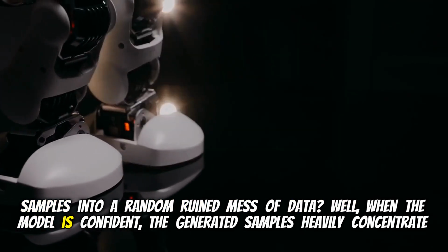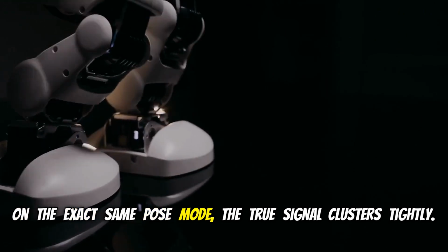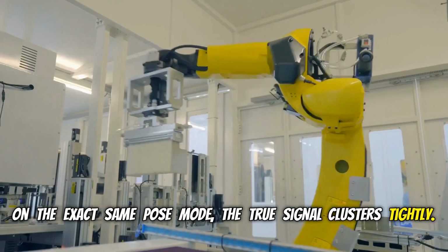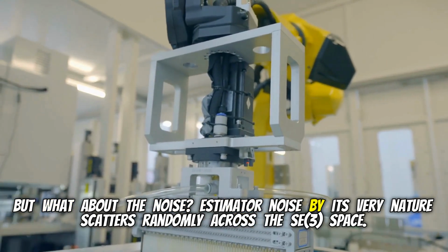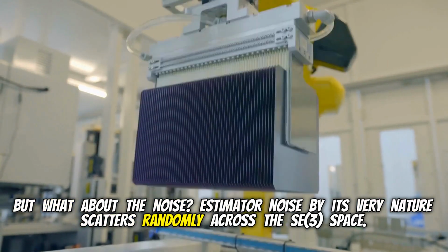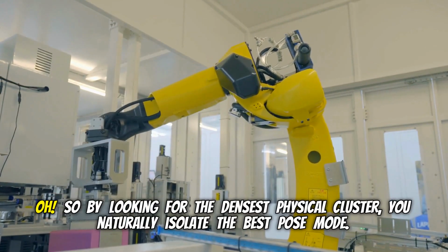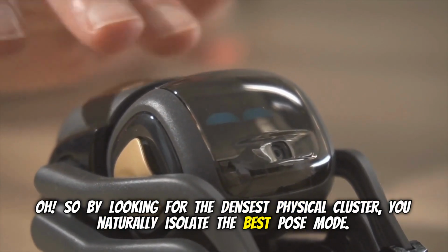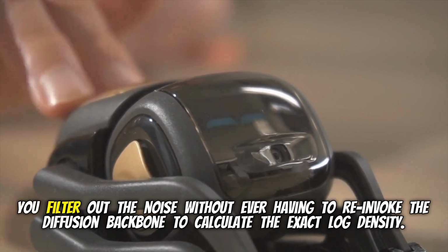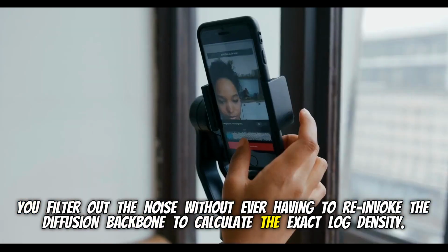Well, when the model is confident, the generated samples heavily concentrate on the exact same pose mode. The true signal clusters tightly. Okay, sure. But what about the noise? Estimator noise, by its very nature, scatters randomly across the SE3 space. Noise doesn't coordinate. Oh, so by looking for the densest physical cluster, you naturally isolate the best pose mode. Exactly. You filter out the noise without ever having to re-invoke the diffusion backbone to calculate the exact log density.